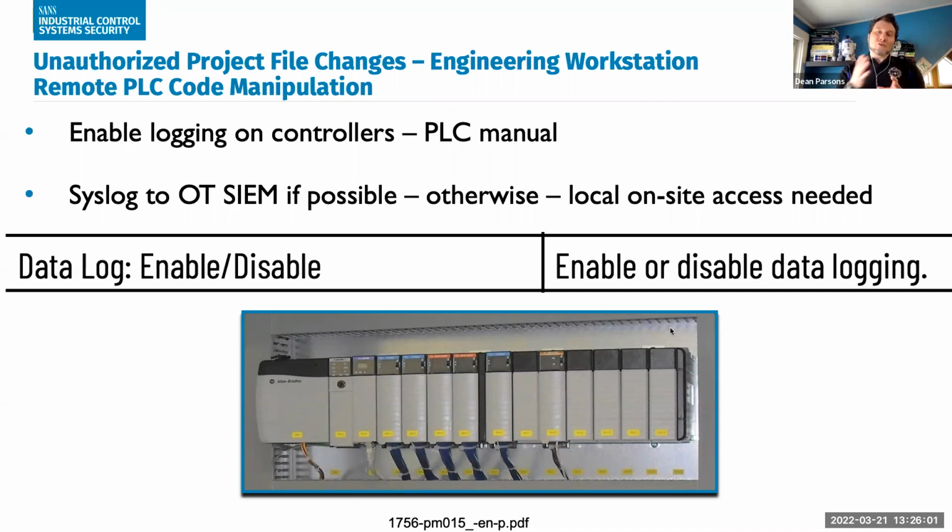Going right back to the first hypothesis we've seen, focusing only on the PLCs here and also just the engineering workstation, do we have any correlation between that, the HMI changes, or any pivoting from the historian? All of this is a really true picture of a stage 2 attack in the control environment. So once we have our logging enabled in the environment, then we can actually pivot to which specific events we're going to gravitate towards first.